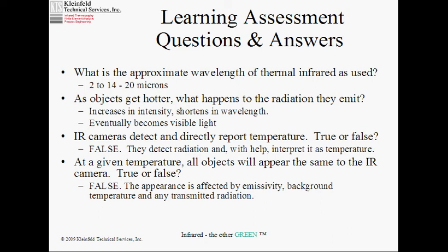radiation temperatures. So if you have a moderate emissivity object, say 7/10, two of them side by side, and one of them is seeing a 1,000 degree furnace behind me as I'm looking at it with the camera, and the other one is shielded from that, seeing room temperature. They're identical, they're at the same temperature, they will not look the same even though they have the same emissivity and they're at the same temperature, because the reflection has changed.